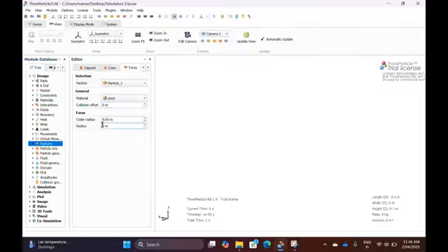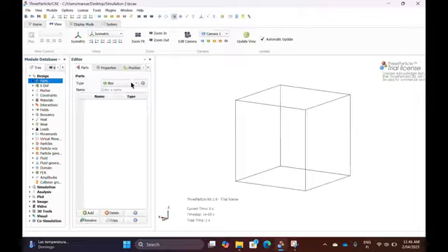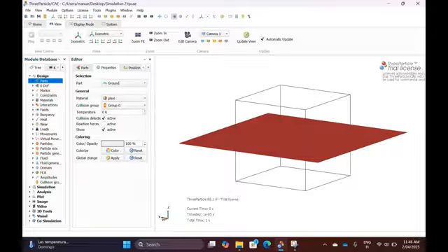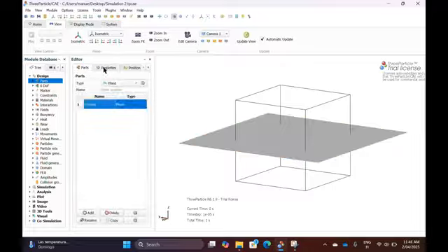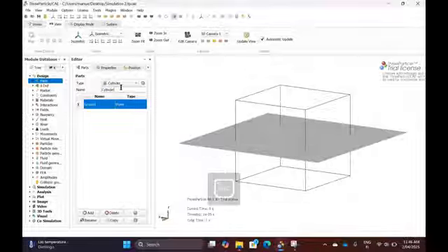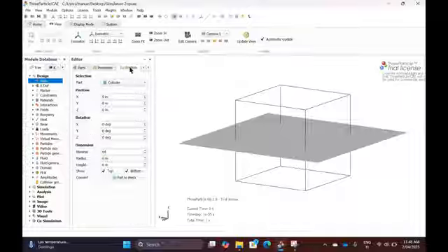Then we define our parts because we want to build something, right? And therefore we need at first a plane. Pre-selected. Okay, let's say plane. We call it round. Double click it. Looks not too bad. Let's stick with that. Then we need a cylinder, obviously. We call that a cylinder. We double click it. And go to position. Here we can define the size of the cylinder.